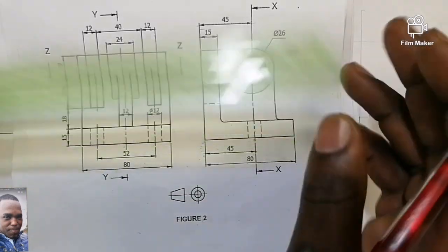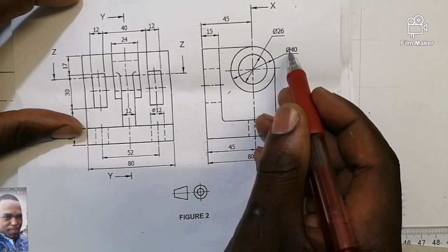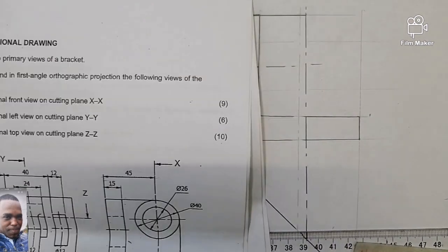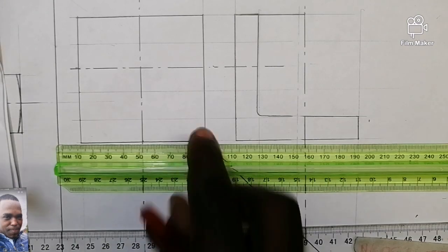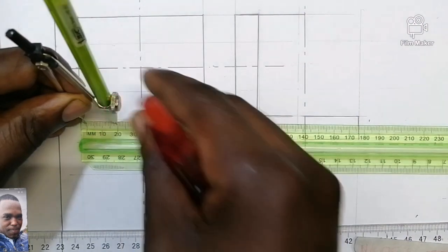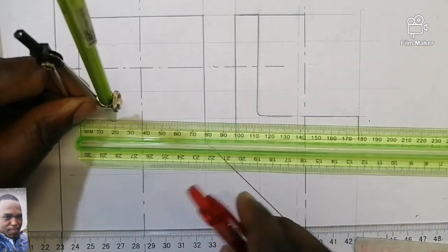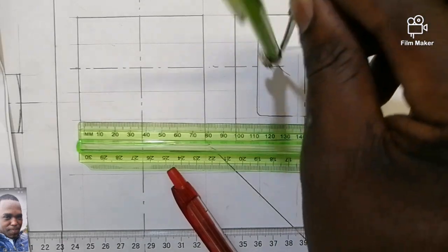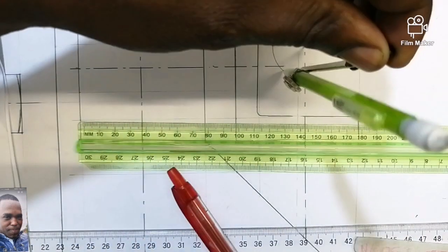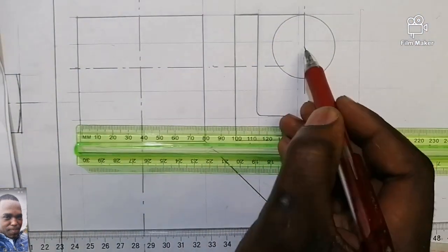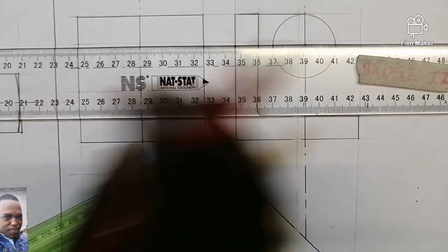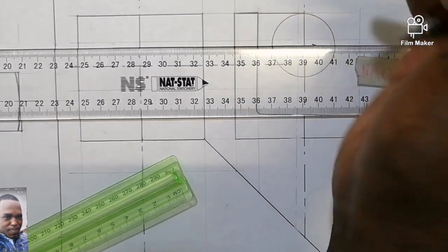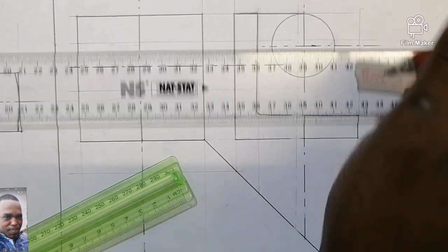So the center, how are you going to get it? You are going to get it by drawing diameter 40. So from there till there is half of 40. Let's do it like this. So 40 divided by 2, you are getting 20, like this. Then draw it dark. You see that what seemed to be missing actually came out for itself. Where were you placing your compass? There. So it just came out for itself. Do you see that it's a little bit below your dimension of 17 millimeter? Like this.